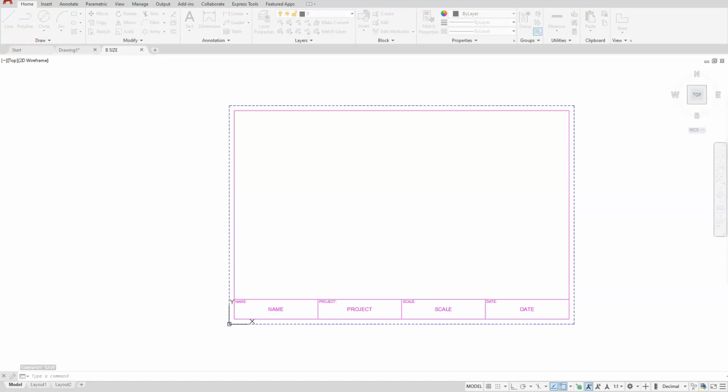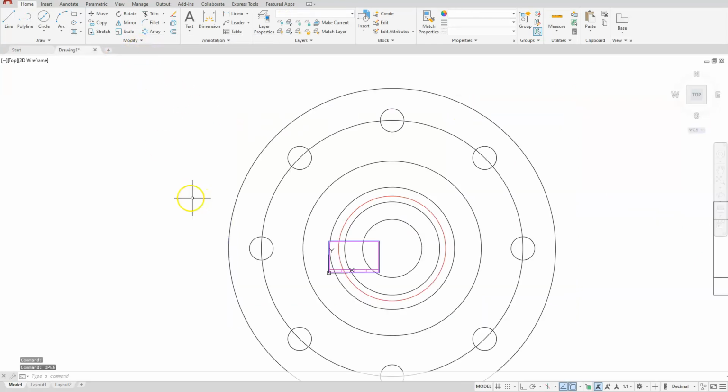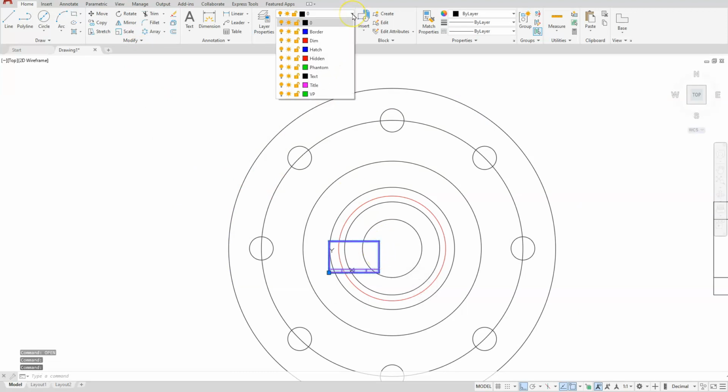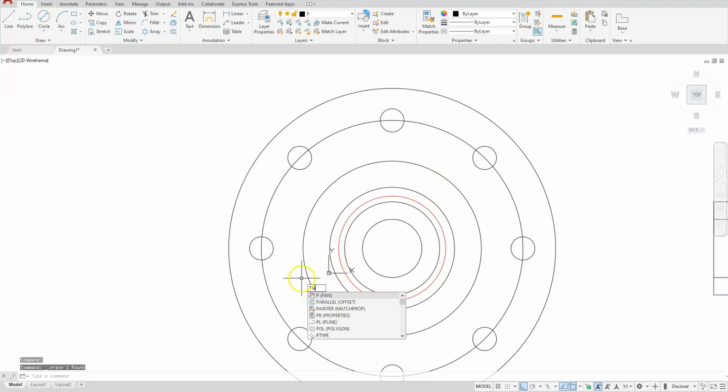And then you can close this dialog box. I'm sorry, you can close the drawing altogether. Alright, so back here, it does not automatically update this. So what I'm going to do is delete that title block. I'll use the purge command. I'm just typing in PU for purge.